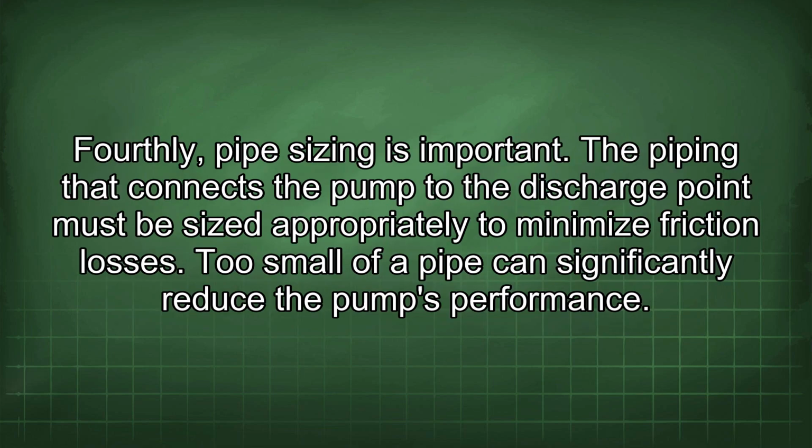Fourthly, pipe sizing is important. The piping that connects the pump to the discharge point must be sized appropriately to minimize friction losses. Too small of a pipe can significantly reduce the pump's performance.